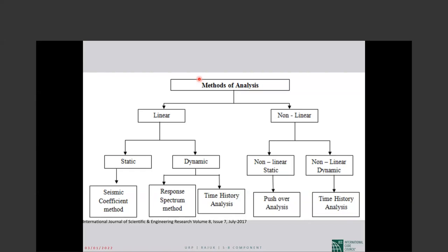When we look at a building, we see lots of deformation control action, lots of force control action. If we look at another building, we see lots of deformation control action, lots of force control action. So, as to the status of these deformation control actions and force control actions in each element, in each type of system, which one is the ductile deformation control action, which one is the brittle one, the force control action, the code for the existing building identifies them.